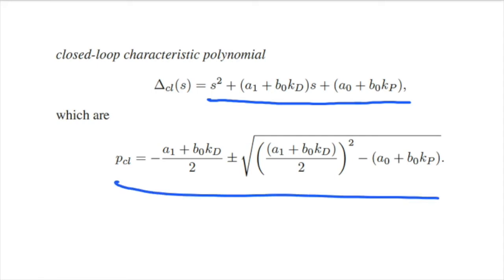Now you compare these poles with the desired poles. For example, let's say I want to place my eigenvalues or poles at -3 and -4, right? There are two poles, so the characteristic equation is s plus 4 and s plus 3. That is the desired characteristic equation. This is what I want. So your poles are at -4 and -3.